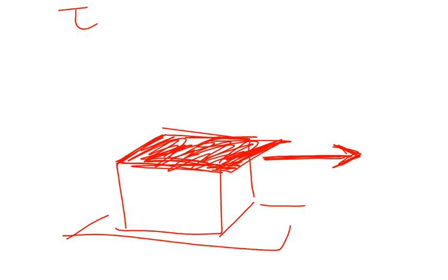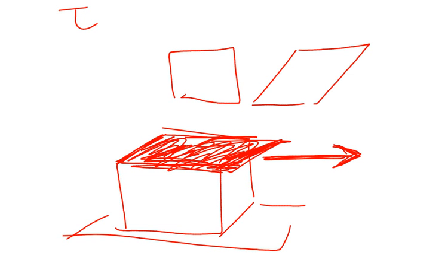And then I just measure the change in angle. You could imagine, if you look from the side, head on, you start off with a square, and then it starts to deform like that. From the figure you just saw, if you just measure this angle, there's your gamma. So you could take a plot of tau versus gamma.